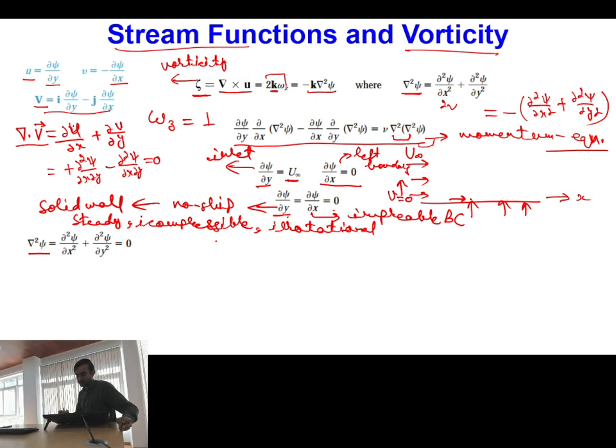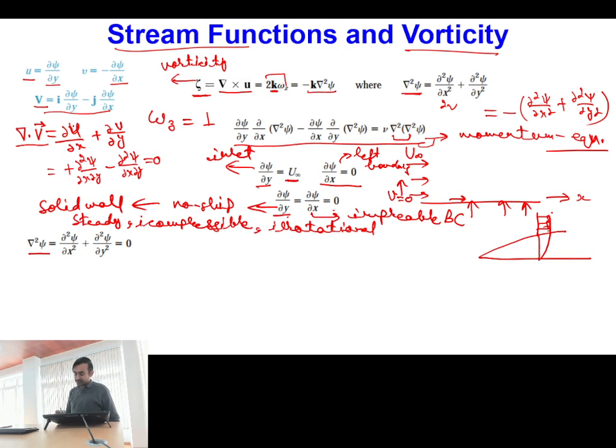So in physical scenarios, if you have a solid plate, you will have some boundary layer portion within which you have variation in velocity, but outside this boundary layer region you have uniform velocity. It means that sufficiently away from the solid boundary, much boundary effect will not come into the picture. So here my flow will be irrotational, and within the boundary layer the flow will be rotational. Is this one clear?